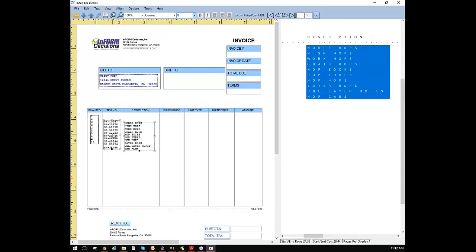If we hold the control button while selecting, we'll select all 3 objects or map fields. Notice I selected the quantity column last. If I go to the align pull down menu and align to the top, it will align to the top of the last object I selected. It's a nice easy way of making things line up.